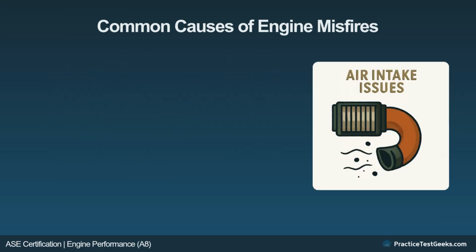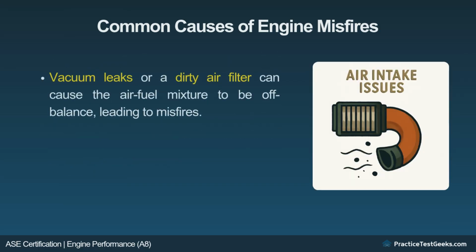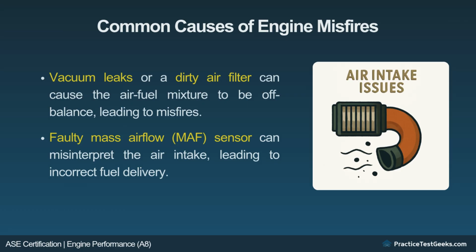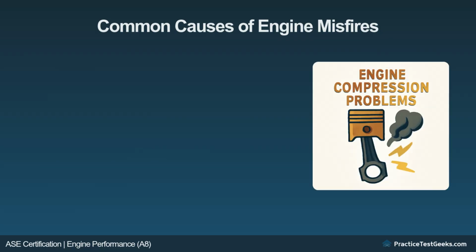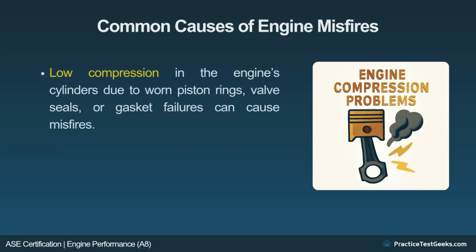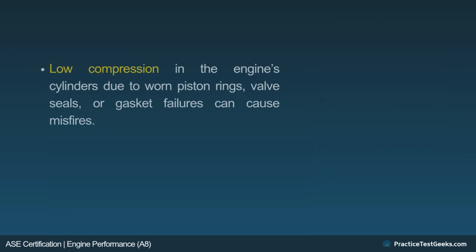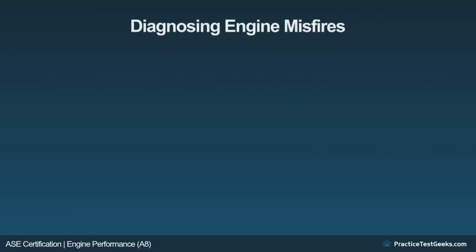Air intake issues. Vacuum leaks or a dirty air filter can cause the air-fuel mixture to be off balance, leading to misfires. A faulty mass airflow sensor can misinterpret the air intake, leading to incorrect fuel delivery. Engine compression problems. Low compression in the engine cylinders due to worn piston rings, valve seals, or gasket failures can cause misfires.